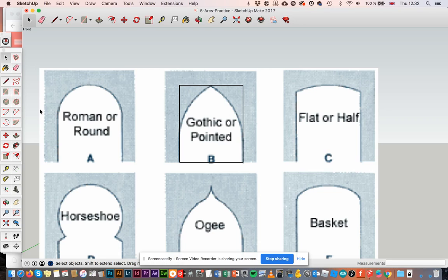I'm going to draw my first curve. I'm even going to draw construction lines on the edge of the curve. It's about here, let's say. Whoops. That's building my rectangle, so I have to, again, erase the surfaces. 2-point arc, and I'm going to go from the middle of my rectangle here to this edge, but it's not going to be a tangent.